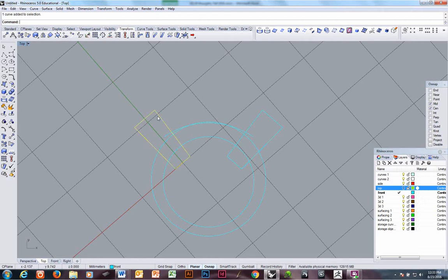I'm going to now, the top is actually the width that I want. So I'm going to move this straight down. I'm going to look at it again and see if I think I get enough taper. Still, I don't. I'm going to turn on the control points, non-uniform scale them again.